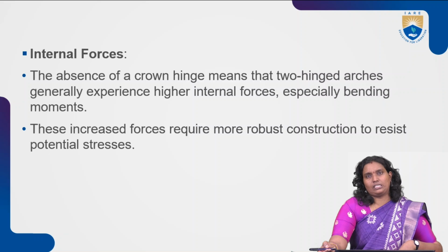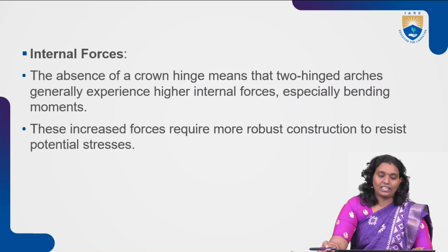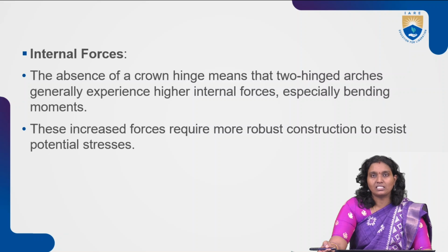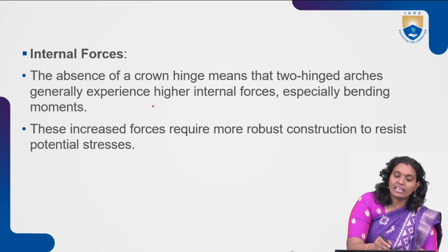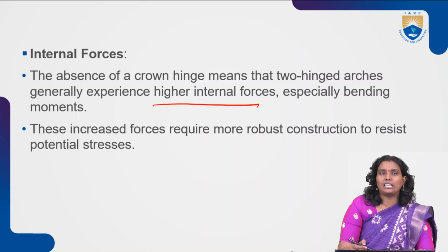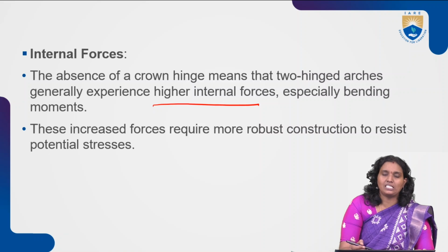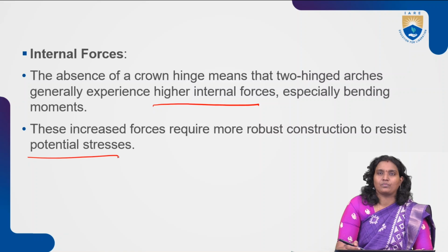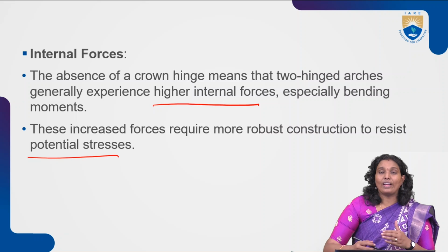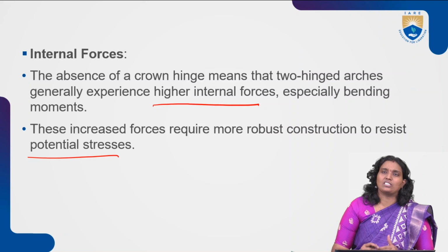And one more structural characteristic is internal forces. The absence of a crown hinge means two-hinged arches generally experience higher internal forces, especially bending moments. These increased forces require more robust construction to resist these potential stresses.